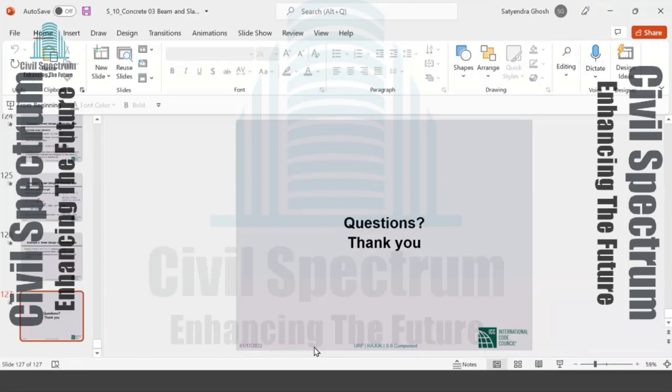But 8 millimeters is very thin. I don't know if you have seen those. Those are very thin bars. Dr. Rakib, do you want to pitch in on that? There is no prohibition, as Dr. Ghosh said, and 8 millimeter bars are not very common. They're used, but they're not very common. I don't know about the cost, but you're right that for lesser diameter bars, more work has to be done at the manufacturing site. So it may be a little bit more costly.